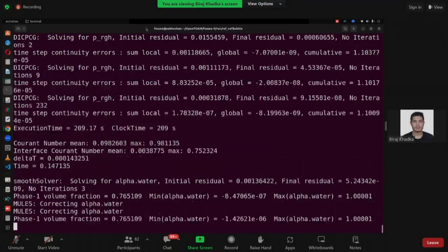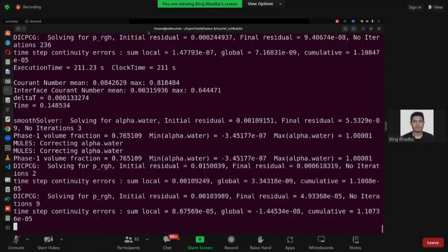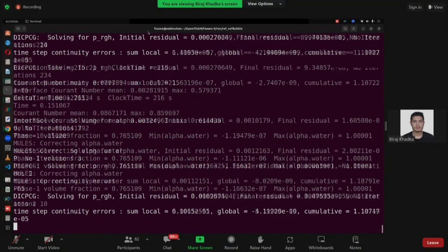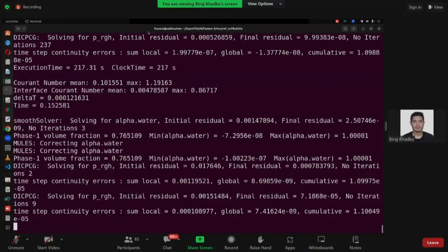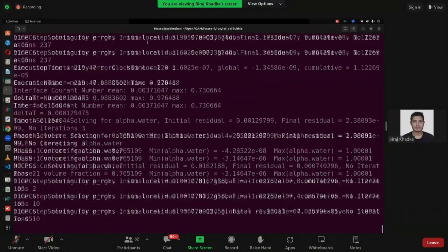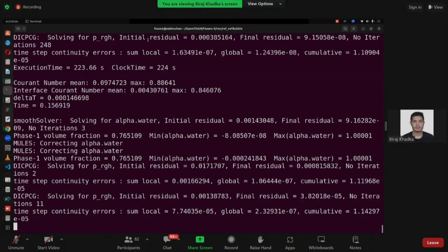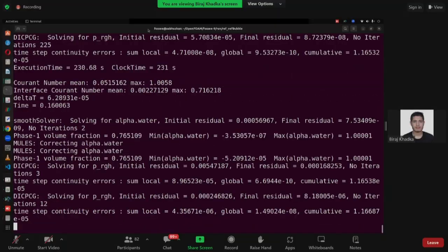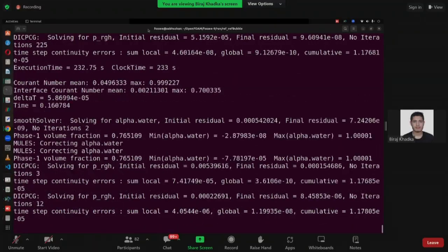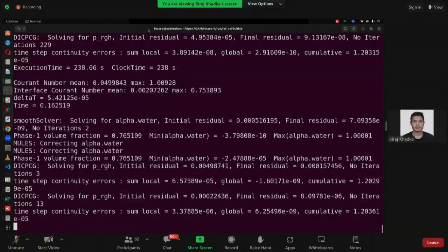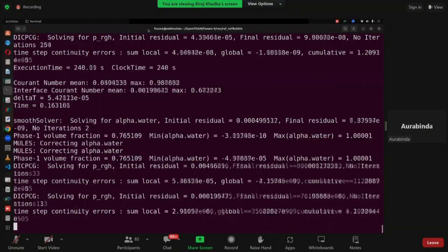Non-uniform can also be defined, but along the patch we have to define it. In order to define the same value, we can define it as uniform. Otherwise, you can give another boundary condition as well, non-uniform as well. Non-uniform means, let's say, a parabolic boundary condition, something like that. Yes, meaning what are the boundary conditions?